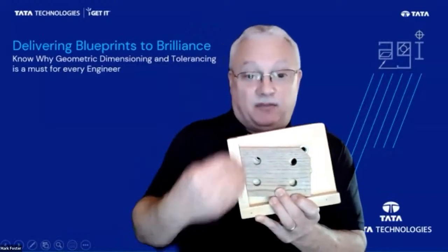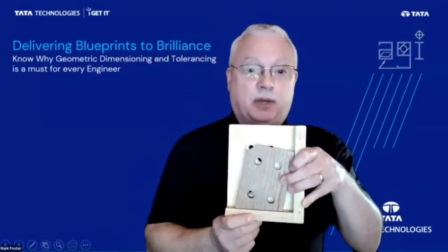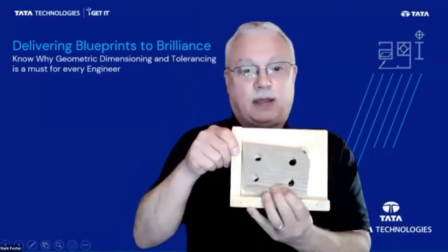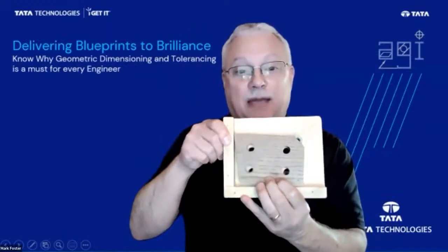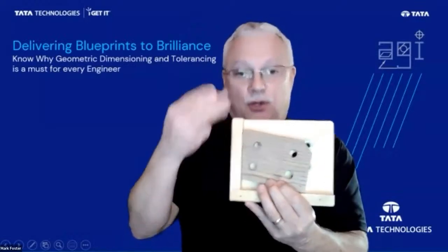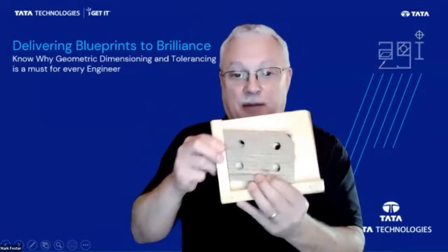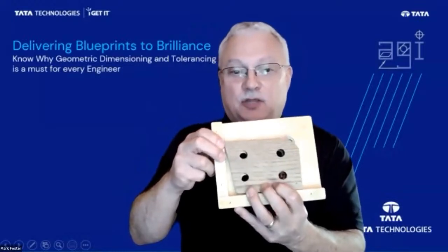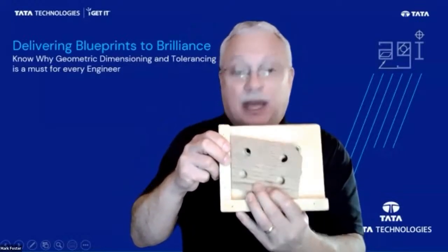The pins don't fit through the holes. And yet I might have measured it this way because I had it set up in my measurement equipment that way instead of this way, and gravity made it go like this. And of course, once again, I'm exaggerating this error so that you can see it with your naked eye. But the bottom line is, that could just be a few microns. That could be a few thousandths.